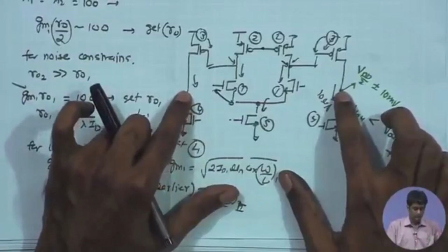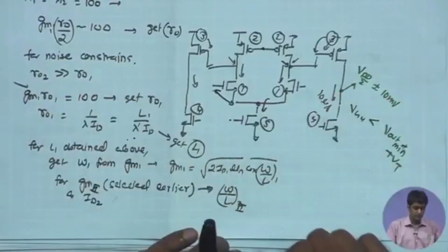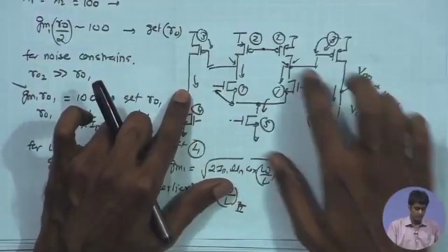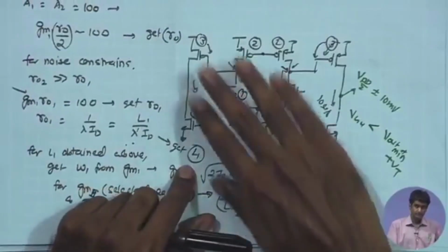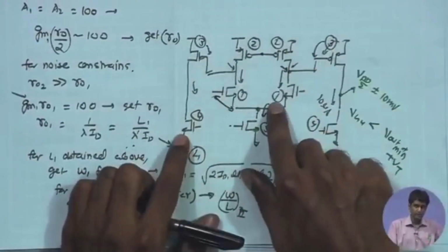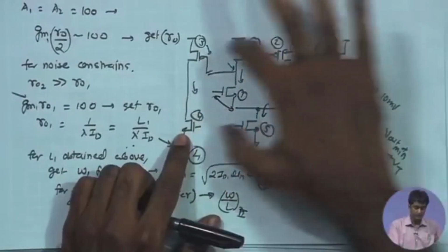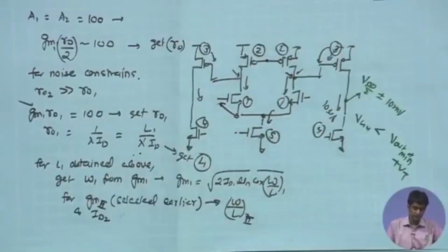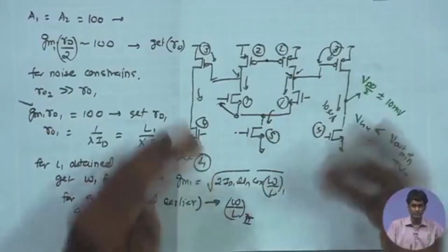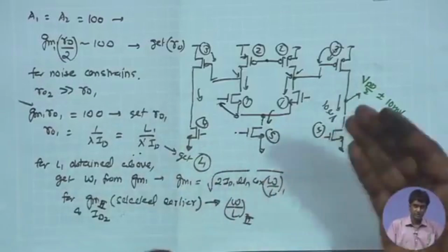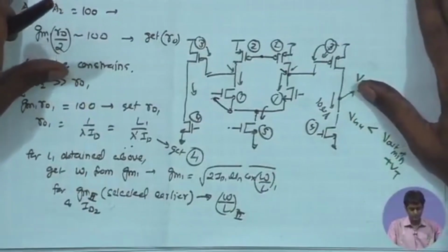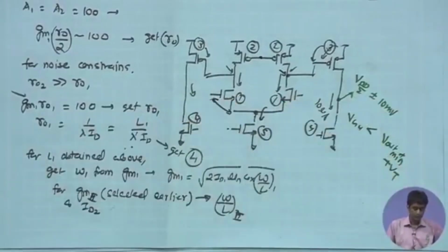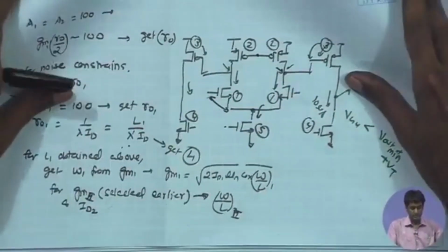And if we look at the input, if you look at the common mode feedback for the joint loop, like if you are having a single loop and if you look at the common mode of the individual loops where you require larger gain for the common mode feedback amplifier, there of course you are using current mirror load for that, and we are assuming GM-RO gain from the common mode feedback amplifier. Some of the constraints related to the common mode feedback can be the input swing, meaning what is the input swing that the common mode amplifier can handle.